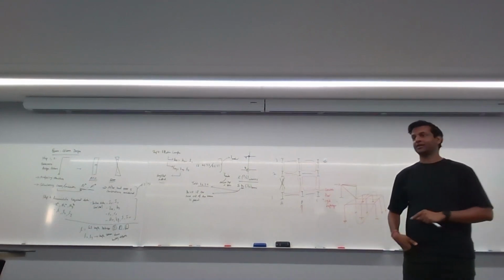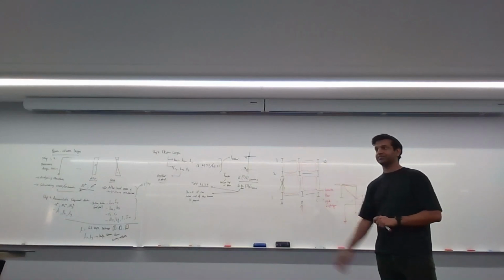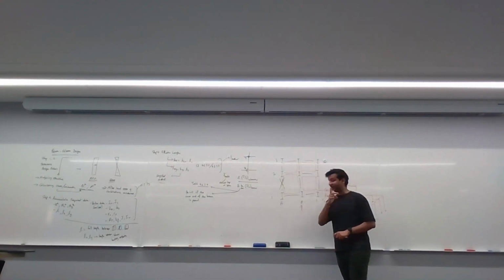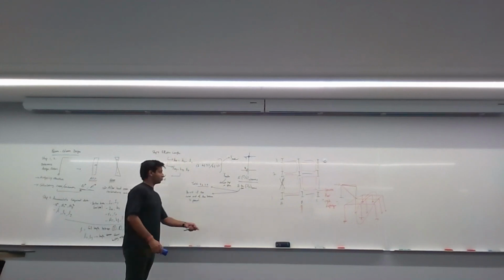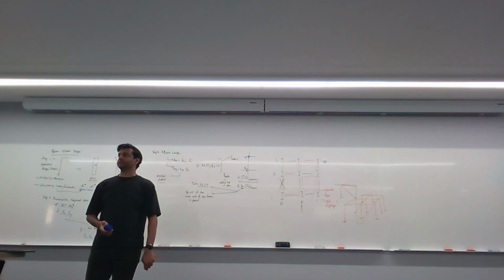Frame 2 is swayed, because nothing is braced in the x direction, as in from left to right, nothing is braced. The direction that's braced is only this way. Anyway, that's really important. So, based on whether it's braced or swayed, use the correct clause and identify the correct gamma value. Any questions on this?